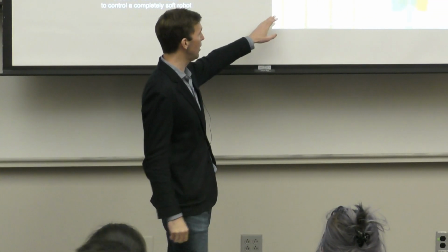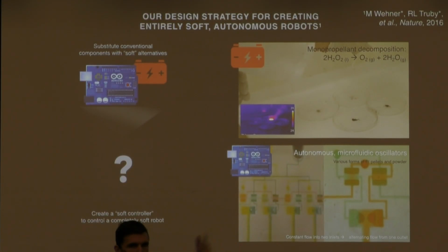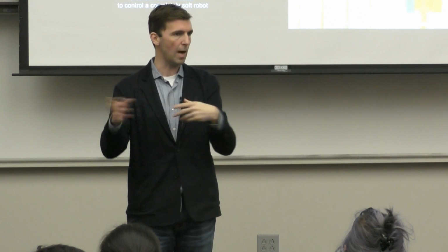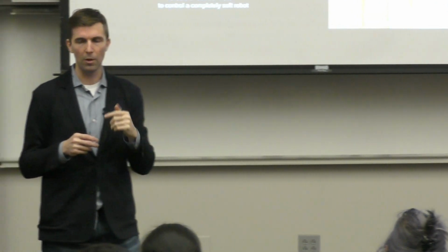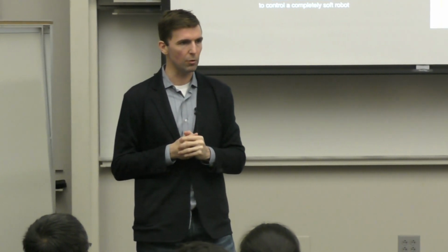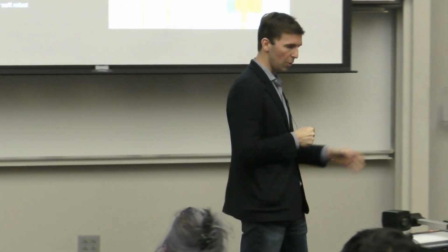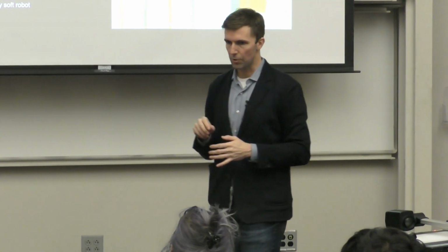This is one example that we took inspiration from, if not directly copied, which is a fluidic oscillator. If I take a single constant pressure input into this system, then it oscillates the output between two different output channels. It's a very simple structure, but it's the first example of a broader class of things that we can do. In fact, we can do the fluidic analogy of almost any electrical system, from the component level up to systems like comparators and sequencers and shift registers, et cetera.